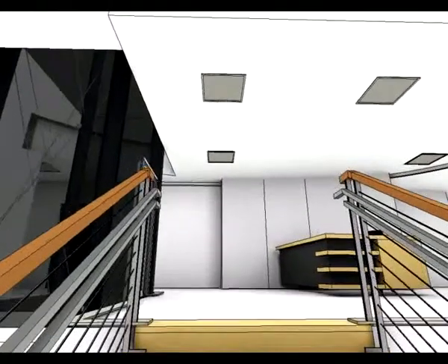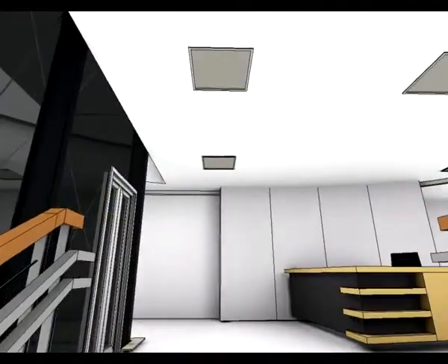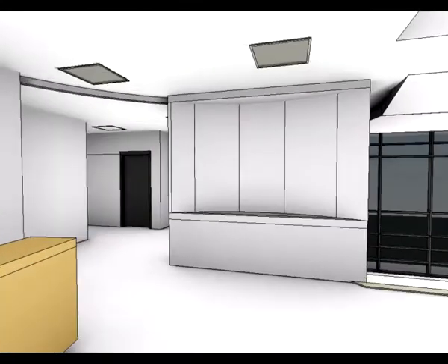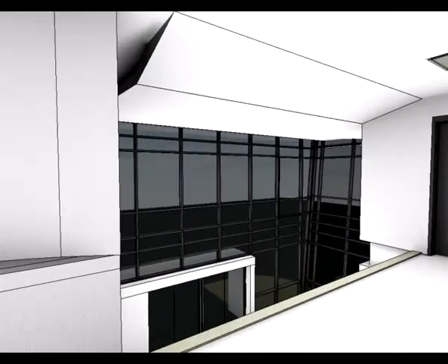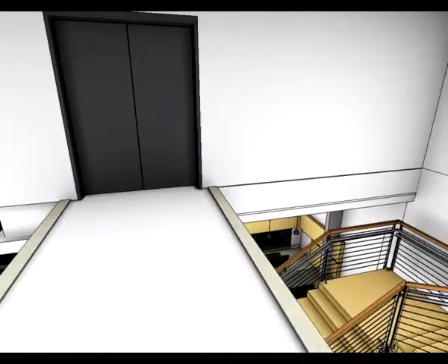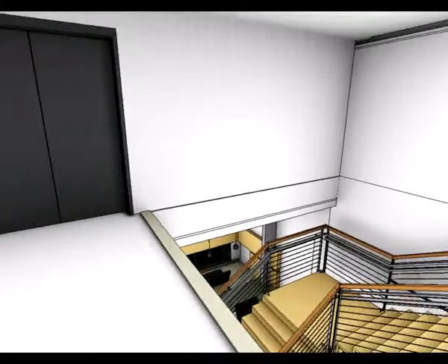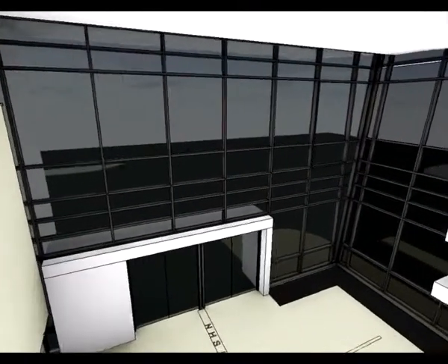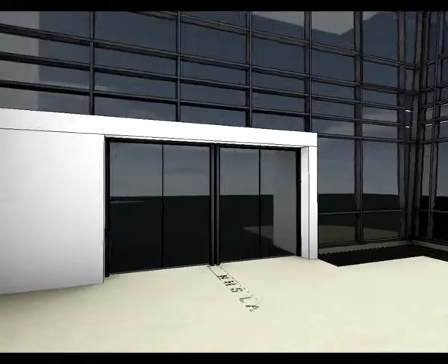The gravity feature recognizes stairs and slabs and keeps your camera above the horizontal structural elements at a predefined distance. By default, this distance is set to eye distance. This greatly helps the walkthrough when you wish to go up stairs or ramps in the building.